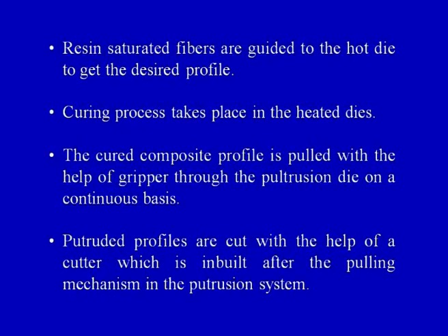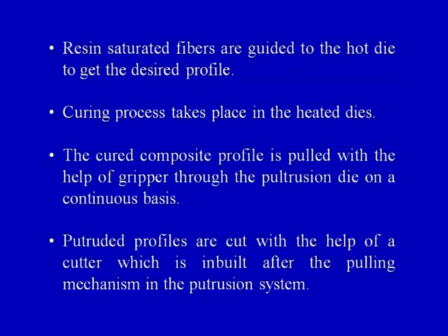The cured composite profile is pulled with the help of a gripper through the pultrusion die on a continuous basis. So there will be a continuous pulling of the pultruded profiles which have partially solidified or solidified in the die itself. The pultruded profiles are cut into the desired length with the help of a cutter, which is inbuilt after the pulling mechanism in the pultrusion system. So, after the pulling mechanism we will have a cut off saw or a cutting mechanism which will cut the pultruded profiles into the desired lengths.